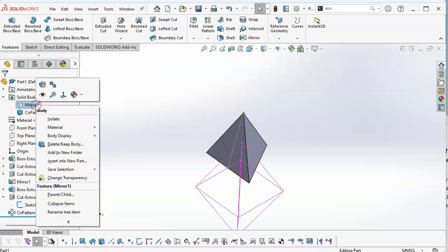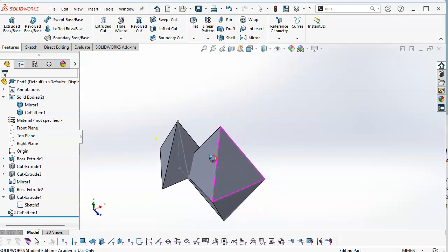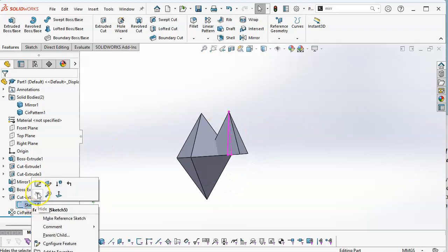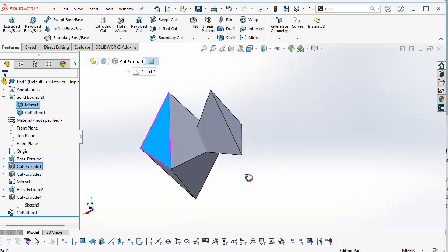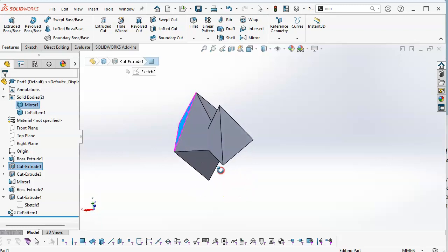And so if I go from this point and I show the other body, now I have 2 separate, and we would go back and clean up and hide the sketch. And one of the things with SolidWorks is this solid body intersecting this solid body, it doesn't care. It's going to pretty much duplicate that mass. If I go to measure it, I am responsible for 2 objects occupying the same space. So keep that in mind as you're creating this geometry.